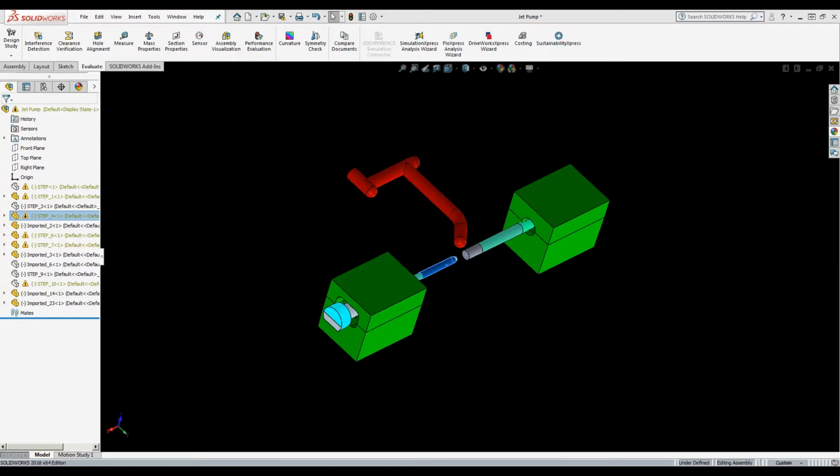The understanding is that, yes, if we have hand loads and removable inserts, in a production environment those could be core pulls, whether hydraulic or mechanical. Sometimes the prototype tooling is a way to prove out whether or not you can actually have a part shape that way, and might need some adjustments in the design phase before they go to production tooling.